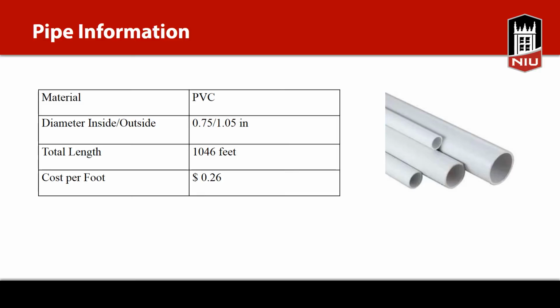Both materials were input into the ground loop heat transfer MATLAB code utilizing the Hardy-Cross method. The total length of pipe required for each material was found. After running the simulation, it was found that PVC would end up being the most cost-effective choice of piping material. PVC also has the advantage of being corrosion resistant without any additional treating or coating.